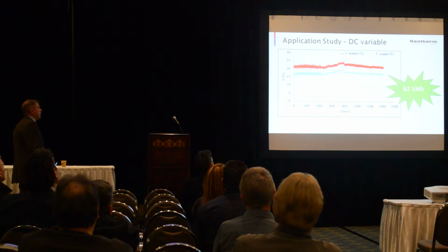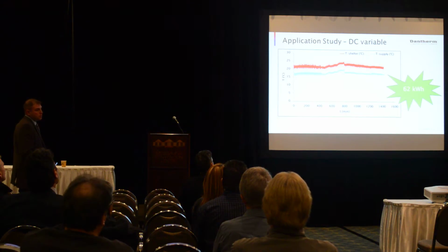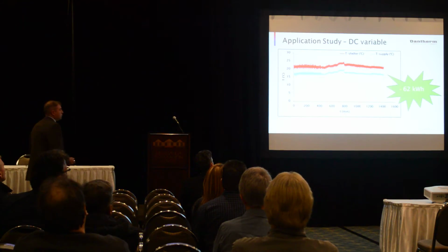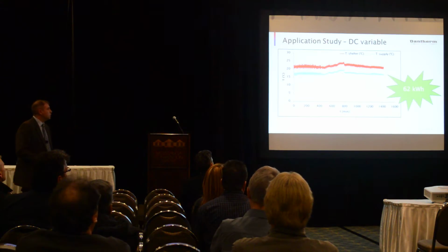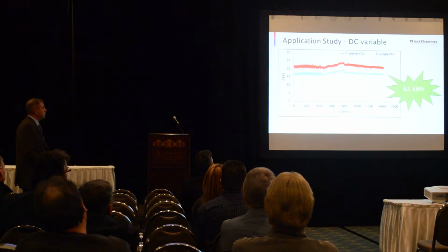And the capacity control is much tighter. That thermal management temperature is maybe 16, 17 to the set point. So it gains even more additional savings. And that's what you want: the precise cooling, variable speed, instead of having that surge up and down, up and down, up and down. You have a nice cool line.